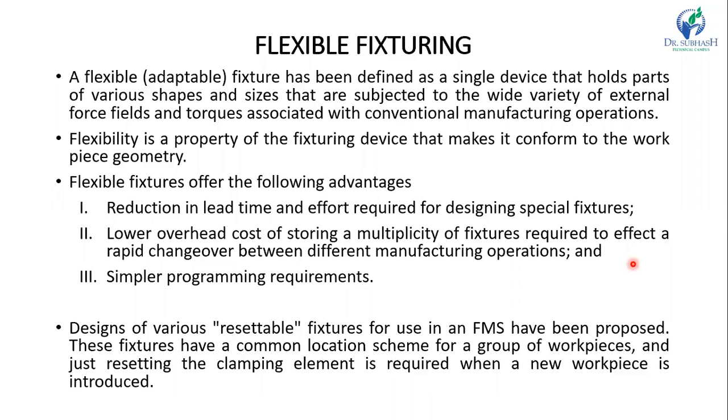So the different advantages of these flexible fixturings are reduction in lead time and effort required for designing special fixtures, lower overhead cost of storing a multiplicity of fixtures required to effect a rapid changeover between different manufacturing operations, and simpler programming requirements.